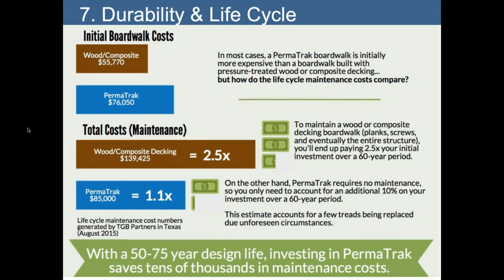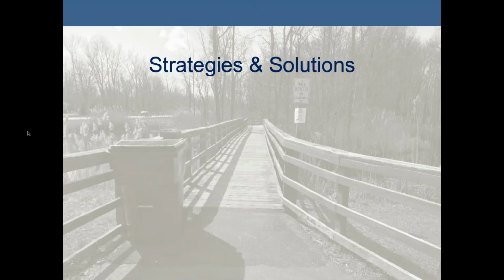The maintenance that goes into a timber boardwalk, as we said, was a negative, whereas with a concrete boardwalk, potentially you may have to clean it. With a wooden or a composite boardwalk, you may have to pressure wash, and over a 10-year span, you may have to replace the boardwalk, which certainly runs up the associated maintenance costs. So this is just an example. Life cycle cost and durability certainly should be part of the equation as you're looking at your design considerations when designing structures through these areas.